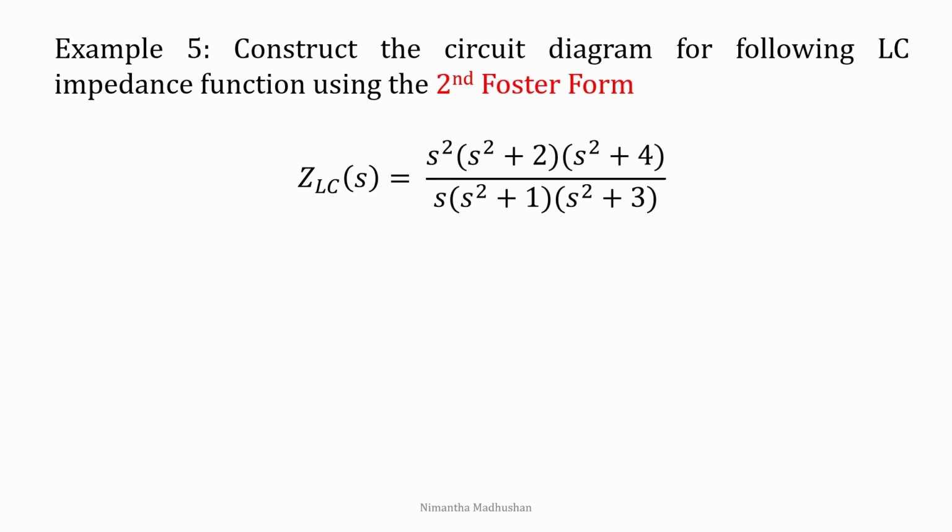In this video, I am going to discuss the LC circuit synthesis problem using the second Foster form. In the previous video, I discussed the same example using the first Foster form. In both Foster forms, we used partial fraction expansion to find the components in the circuit. In the first Foster form, we use partial fraction expansion for the given impedance function, and in the second Foster form, we are using partial fraction expansion for the admittance function.